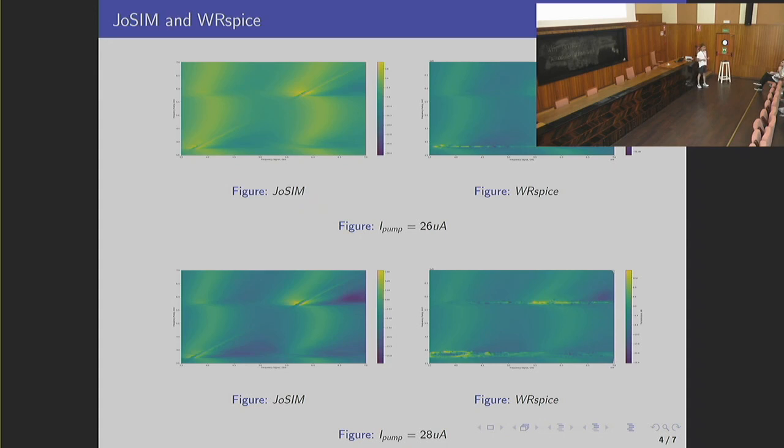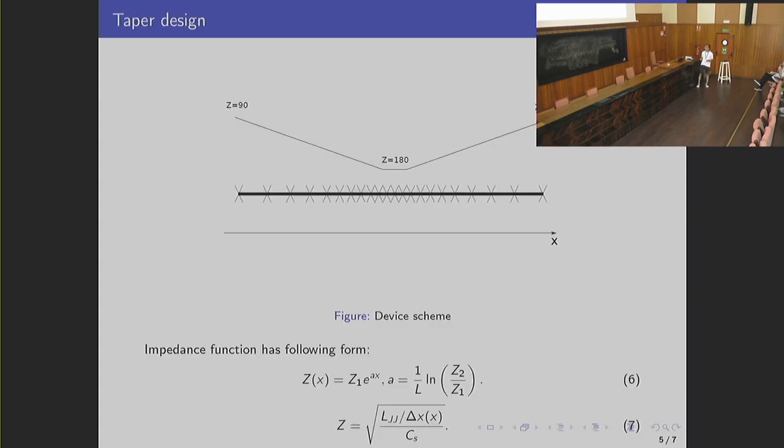We can simulate the impedance, because impedance is a purely classical quantity. So what's the point of such impedance? We can actually make a very nice amplifier with a big gain and big range. But if it is not impedance matched with our input, which is usually 50 ohm, we will have so-called ripples. If we have a big impedance mismatch, some frequencies will be amplified, but other frequencies will be suppressed, because almost all power in some frequencies will be reflected.